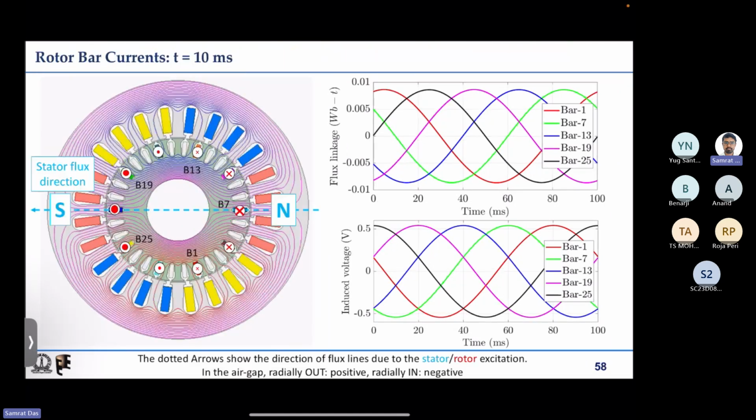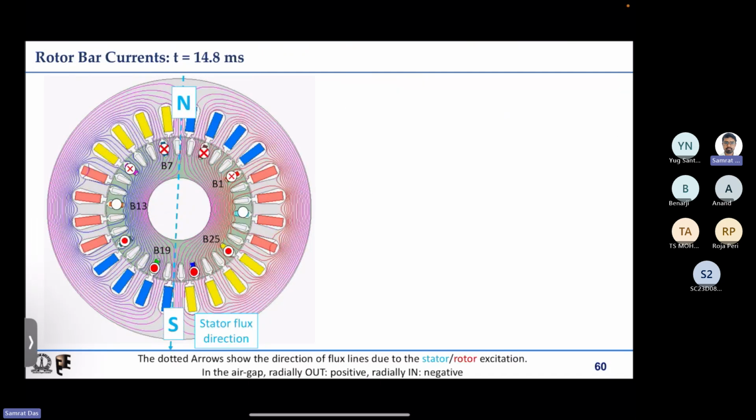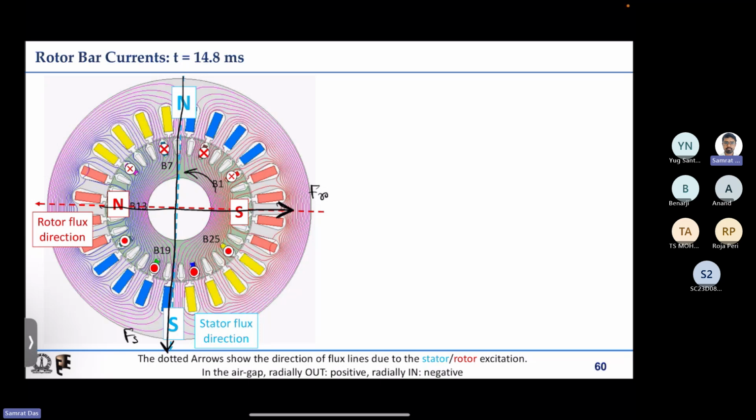So this also we have seen for different instances, and we saw that if we follow the same thing in this case, if this is the stator magnetic field direction, we are taking direction from north to south, then for the rotor, if we take the same north to south, then you can see in this case fr is actually leading fs, because direction of the rotor is still the same.